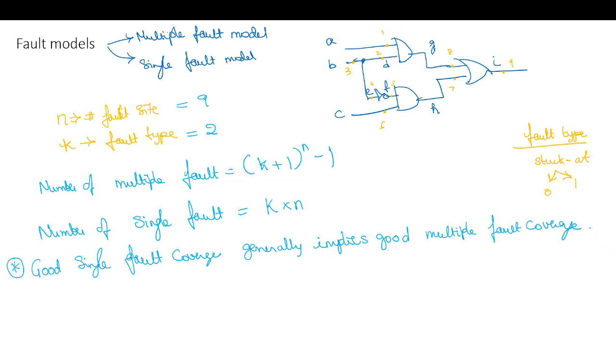And so now with this, you can see that for this small circuit itself, there are 9 fault sites. Can we reduce this further? First, we had multiple combinations. We reduced it and said that single is sufficient. Now, at the single fault level itself, we have so many fault sites. Can we reduce that? That is our next step. So we come to a concept of equivalent faults and fault collapsing.